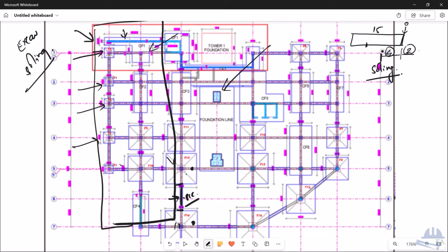All right. So let's say that at this point you start the soling at day -4, but you could have started this at day, let's say, -10 over here, right? Which means that you have got a slack of 6 days over here. So you can adjust this slack anyhow you want. You can start here, here, here, here, or the latest start date is this one, right? So this is the float available to you and you can utilize it anyhow at the site. It's up to you.